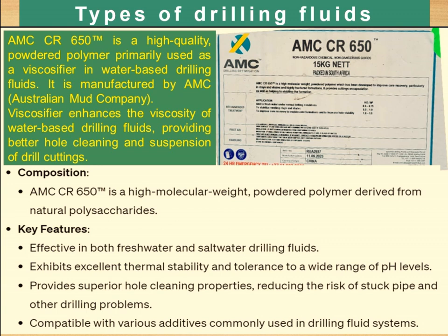So this polymer is primarily used as a viscosifier. Large polymer means high viscosity. This much you must understand. High viscosity means it can resist flow. So high polymer material cannot flow very easily. So it is used as a viscosifier in water-based drilling fluids, which enhances the viscosity, providing better hole cleaning and suspension.